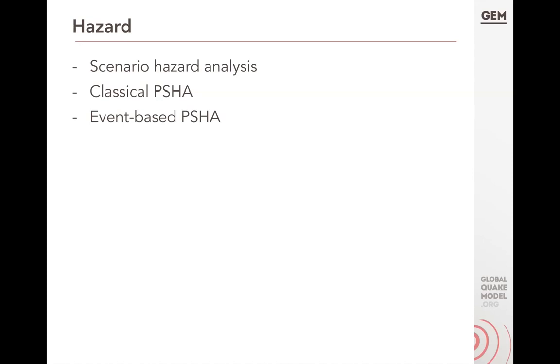So this is going back to the original publication by Alan Cornell in the 1960s, which goes through seismic hazard computation at a single site or a group of sites through a numerical integration approach. So combining the contribution from all of the sources surrounding this region of interest that might be contributing to the seismic hazard at those locations. So you calculate the seismic hazard contributions from all of these and sum them up to get your probabilistic seismic hazard at those sites.